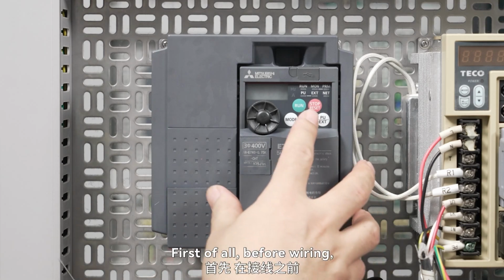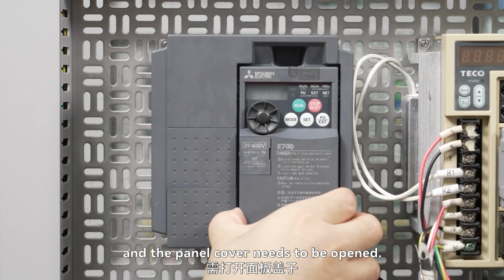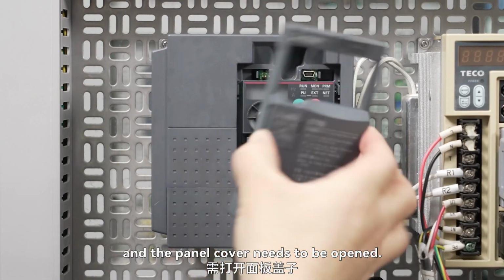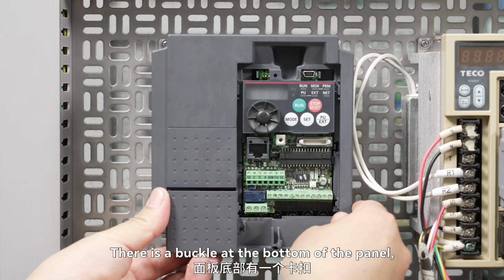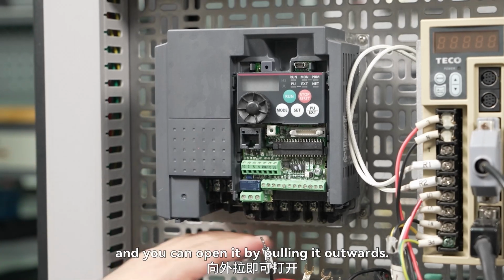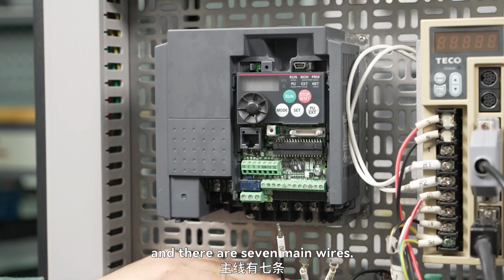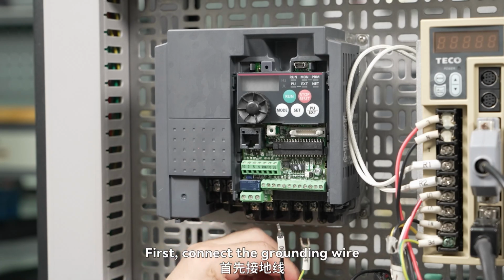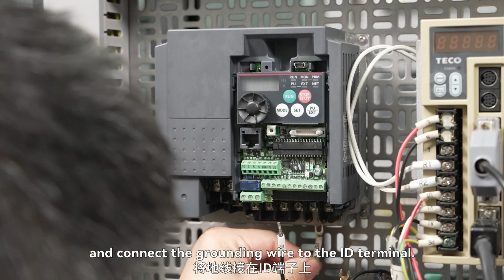First of all, before wiring, the frequency converter has been installed here, and the panel cover needs to be opened. There is a buckle at the bottom of the panel, and you can open it by pulling it outwards. There are many wires here, and there are 7 main wires. First, connect the grounding wire to the ground terminal.